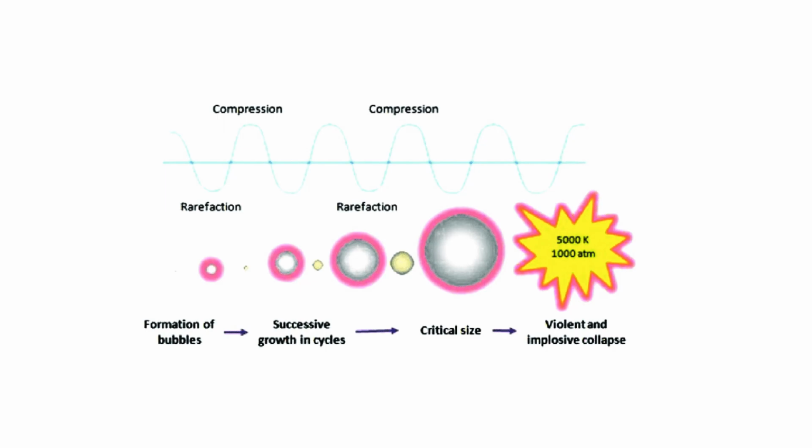So you can see that here the cavitation bubbles. The vapor bubbles, called cavitation bubbles since they form cavities in the liquid, collapse as they are swept away from the low pressure regions, generating highly destructive, extremely high pressure waves. You can see in the figure that the bubbles continuously expand and finally collapse, releasing huge energy which can harm the equipment, particularly hydraulic machinery.